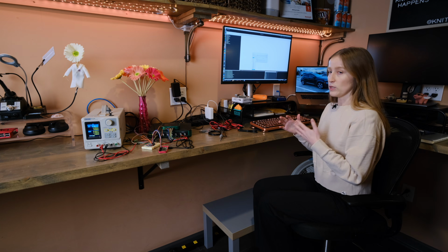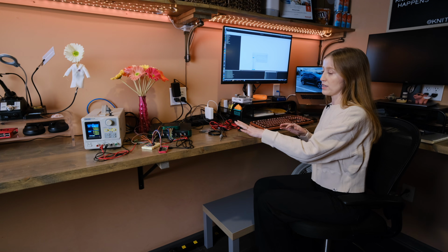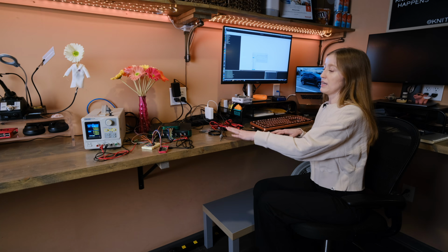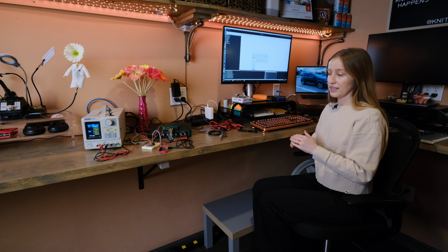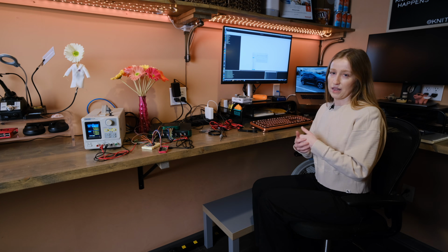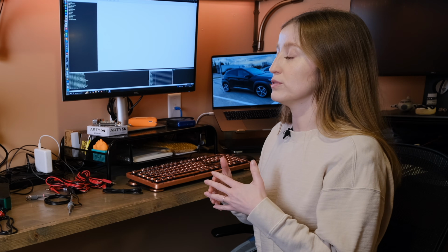Realistically, for the best performance I've found, I set the time base for my target device to be as high as possible, and then I run my worksheets at about half of that. That gives me the best fidelity in my data.